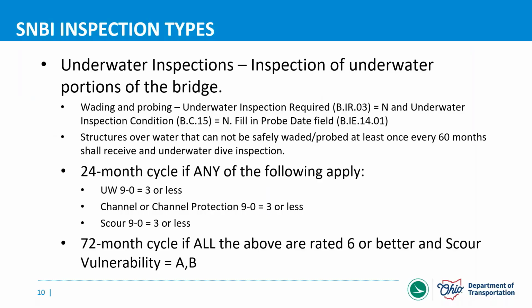So notice that is a shall and not a should. Conversely, if you have a bridge that is marked underwater inspection required, meaning it's typically dive inspected underwater, say you have a year in between your dive inspection intervals where the water is extremely low and you can get out there and actually do a probing inspection, you can replace that underwater inspection date with the date that you safely probed the substructure units while still keeping it as a yes for underwater inspection required.